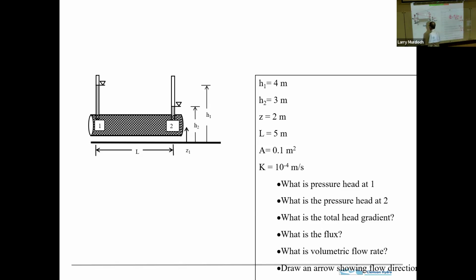And we can get the groundwater flux from Darcy's law. It's K times dh. I didn't write it as dh/dx because we're not really saying that x, although we could say there's the x direction, in which case we could write this like so. And that's going to be 0.2 times the hydraulic conductivity, which is 10⁻⁴ meters per second. So that's the flux, groundwater.